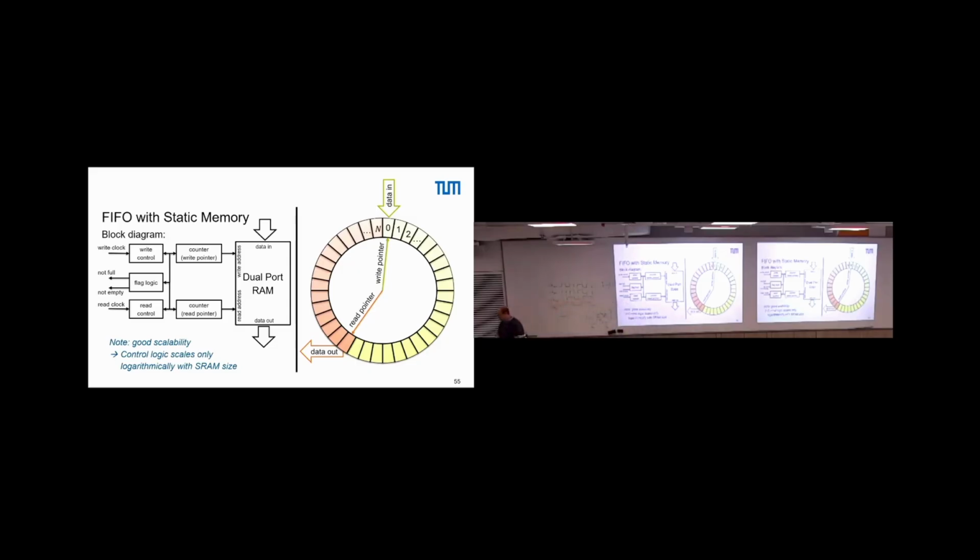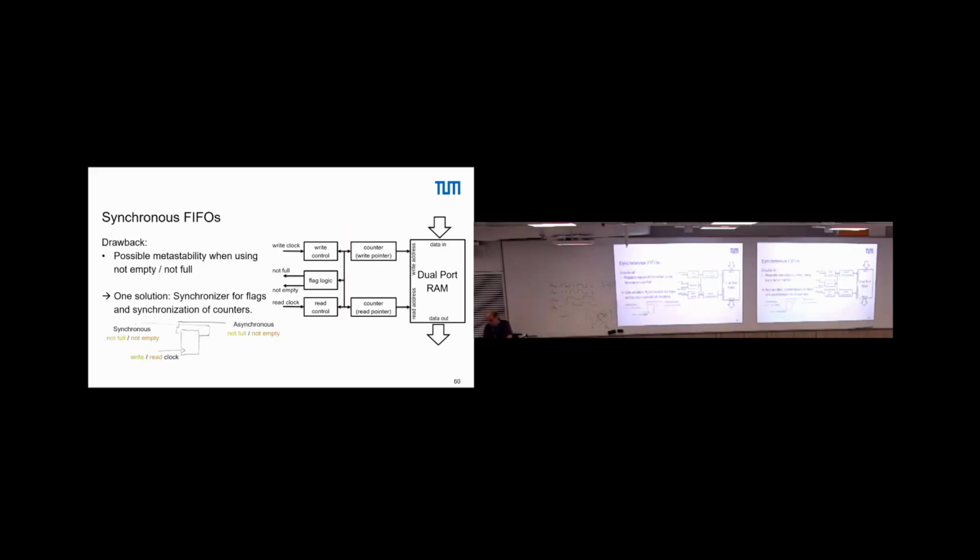Good. So to avoid this, what we can put is we can put some synchronization into these read signals. If I want to include the synchronization into this FIFO, then I have additional requirements, because if I want to synchronize, this implies that I have a permanent clock. Only with a permanent clock can we see that there is some data. If we had some clock that is only triggered by the read, only if we read would we update the full empty signal, and that's not what we want, right?